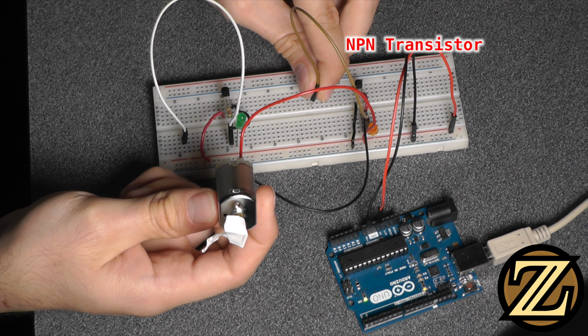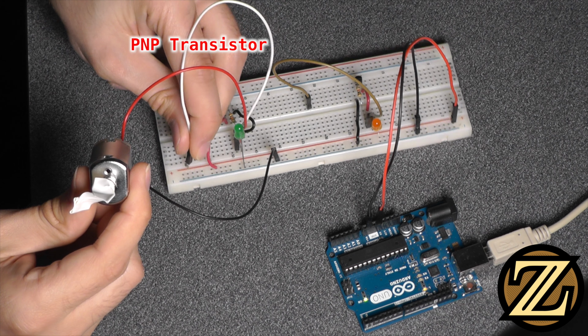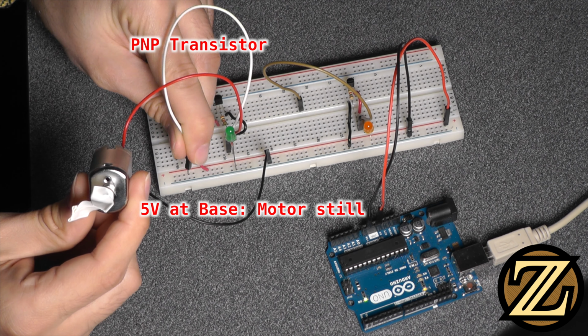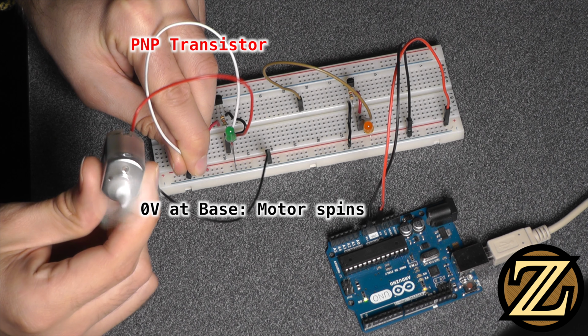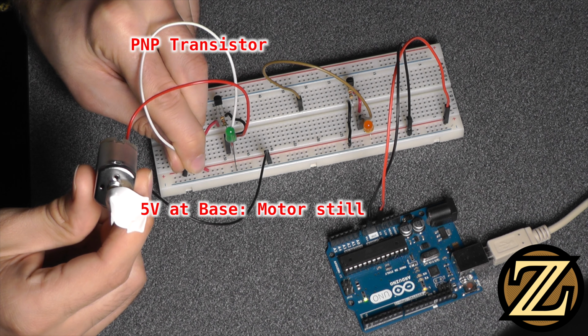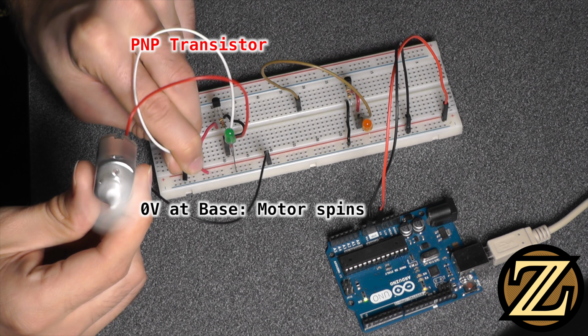Now I am rewiring the motor to connect it to the PNP transistor circuit. When I apply 5 volts to the base, the motor stays still. When I apply 0 volts to the base, we get the motor to spin. 5 volts again keeps the motor still, and again 0 volts winds up the motor.